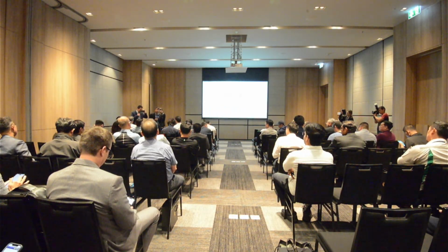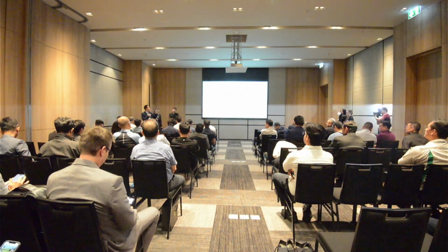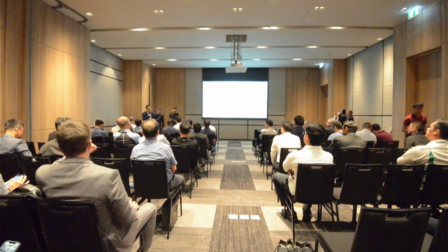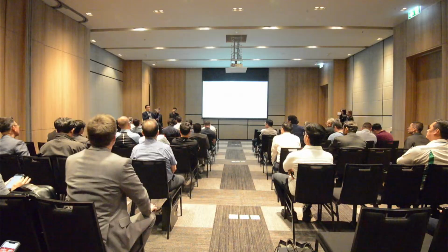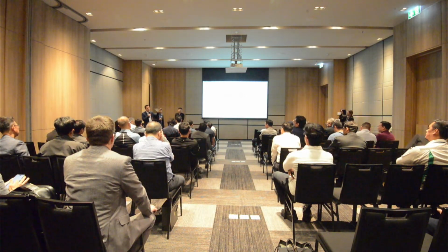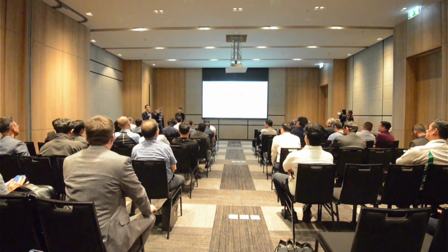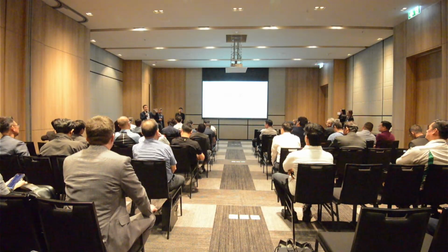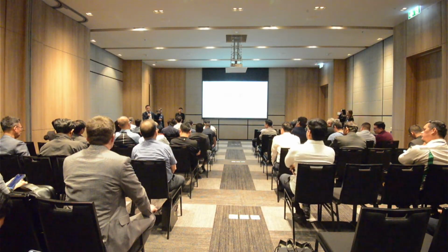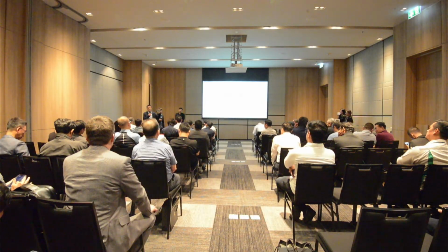His question is how to confirm the in-gate area. First, we know the volume of the casting is fixed. We know the filling time, how long you take to fill the cavity, maybe 20 or 40 milliseconds. Volume divided by time gives the gate flow rate. The gate flow rate equals the gate area multiplied by the gate speed. Then you have to fix the gate speed. How about 30 meters per second? With the gate velocity, you get the gate area.